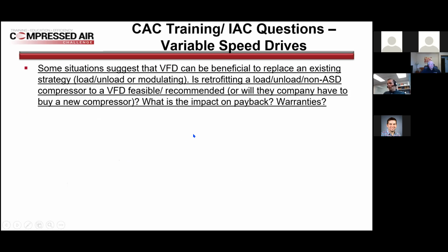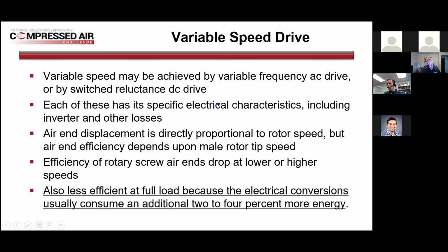VFDs, existing: is retrofitting a load unload feasible and recommended? What's the payback? Variable frequency drive, this is just pulled from some of the compressed air challenge material. But again, the real question with this one is, can it be done? The answer is yes. Is it recommended? I would say no.